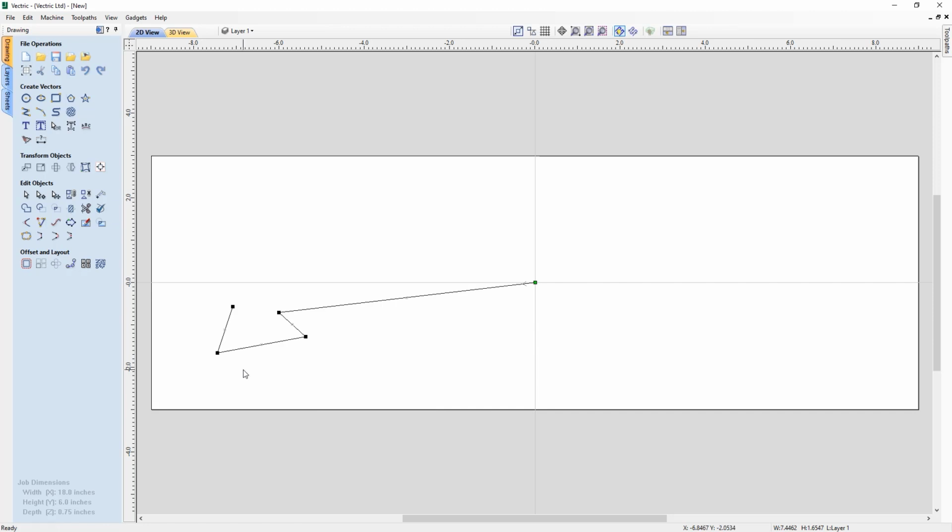But what I like to do here is actually go ahead and reselect that vector and select all of these nodes by using my box selection. That's holding down my left mouse button and dragging, and then pressing S on the keyboard. You'll see what I get. Now I could have easily gotten this by dropping and leading my left mouse button down like I showed you earlier and turning each of those straight lines into curves as I went, but I find this a little bit easier to manage in my head.